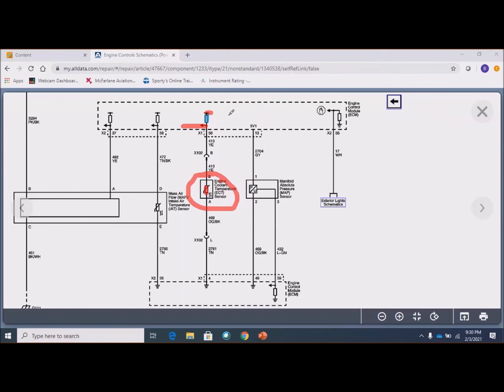So if they are identical, and this is reading 2.5 volts right here, and all of a sudden this one starts dropping less, this is dropping more, this voltage level here is going to go down. Most of you so far have seen that in the shop, but that's how these circuits work. Using the voltage drop on this series circuit, the fixed resistor never changes, but its voltage drop is affected by what's going on out here. And the voltage measured here is affected by what's going on out here.